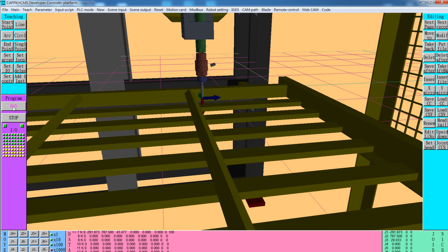Let's run and have a look. It seems okay. Then we duplicate another one at this side with 10 millimeter distance from the edge. So the total is 37 wide. Subtract 10 at this side, subtract 10 at this side. So the moving distance should be 17 in minus position.